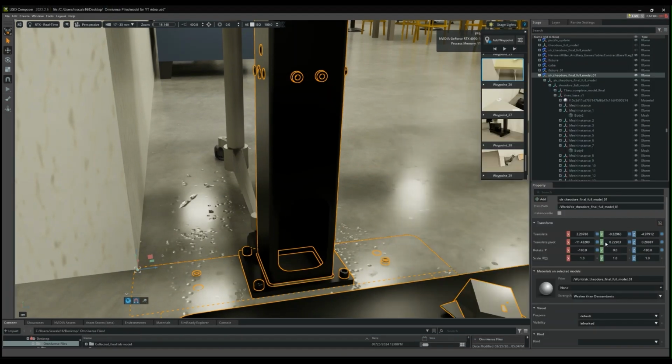I prefer to make most of my movements using the translate option over here. So I think this transform tab itself would be your best friend right now. And one thing I forgot to mention before is always note down your Y value before you move your object to snap somewhere, because as you can see, the model has gone under the base ground level.